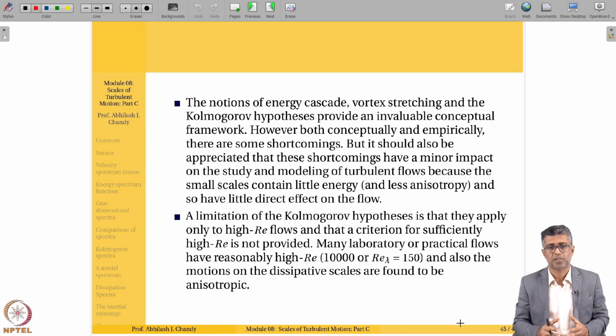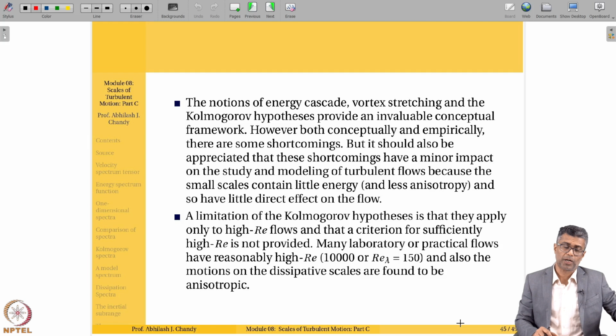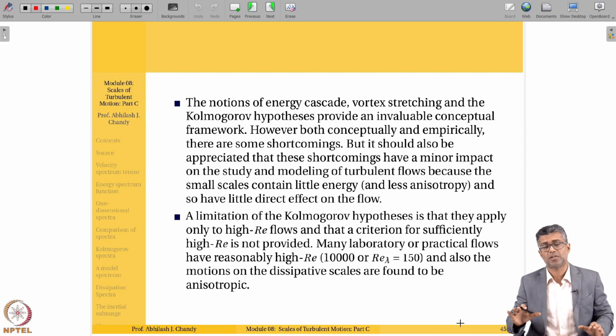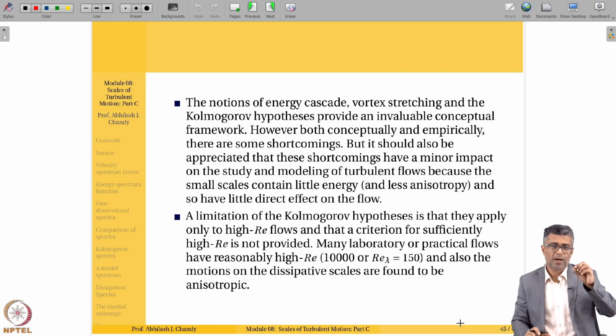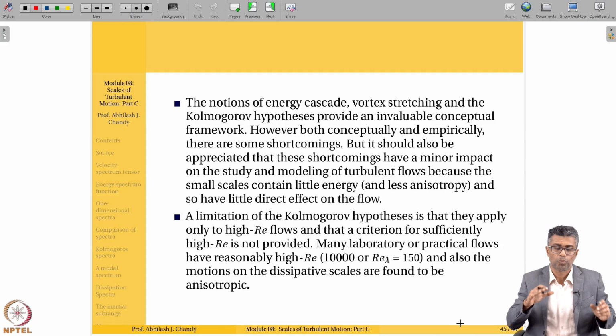And the reason why we say that has to do with when we looked at this cumulative turbulent kinetic energy, we noticed that 80% of the energy is contained in the energy containing range. 80%. Only 20% is in the very few scales below that, and even at the smallest scales, mostly 10 to 15% of the energy is contained in the dissipation range.